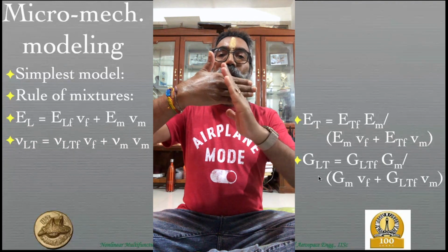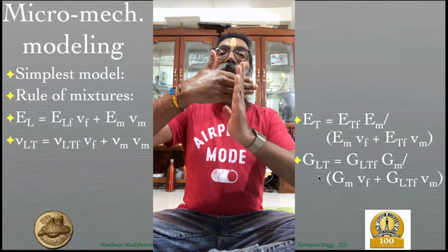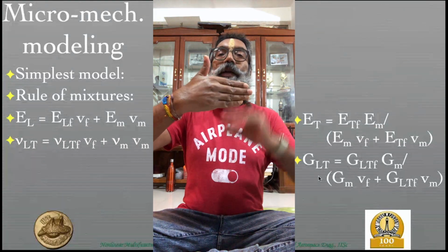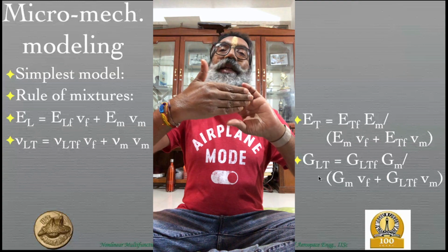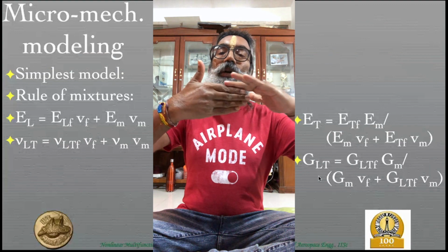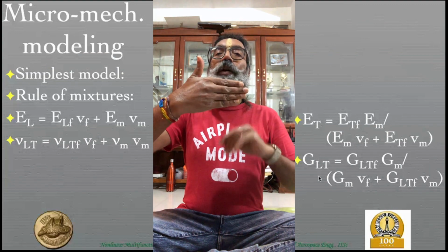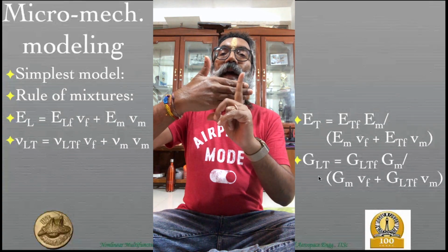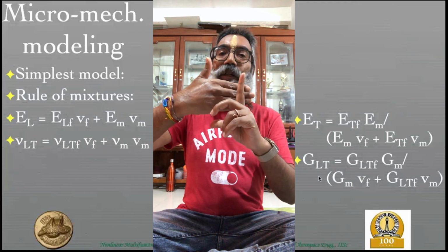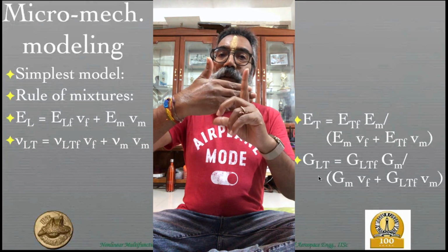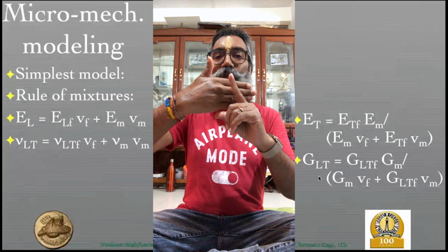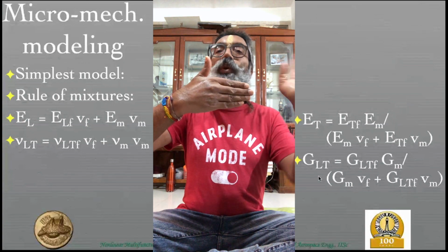The amount by which that right angle is going to change is a measure of your transverse shear strain, and it is these two quantities that the shear modulus GTT prime relates. That is, what is the shear stress that you're applying, which is tau T prime, divided by the change in the right angle that you have over here, which is gamma TT prime. Once again, there is a difference between the engineering shear strain and the tensorial shear strain, I'm sure you're all aware of that, by a factor of 2, taking that into account.